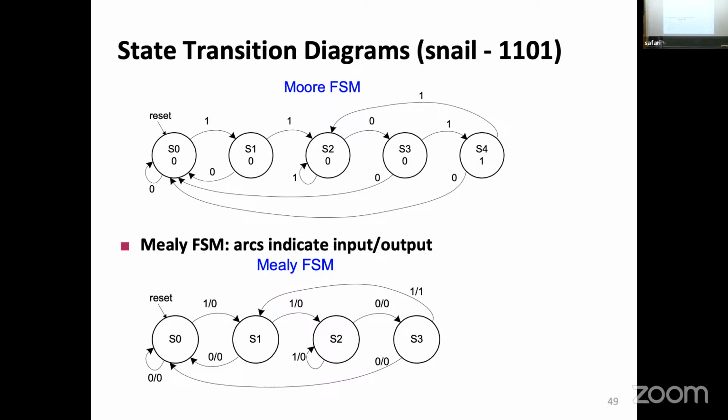Notice that I'm asking these questions in the exam. A possible exam question is, I show you a state diagram and I ask you, is this a Mealy or Moore machine? Very simple trick. Check whether or not the outputs are written inside the state or they are written on the edges as this. This one is Mealy, this one is Moore. You get your points, you are welcome.